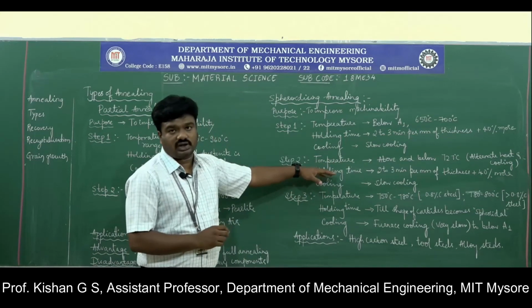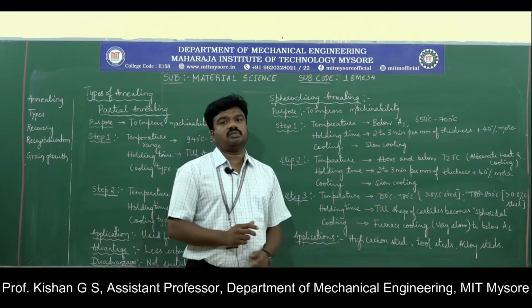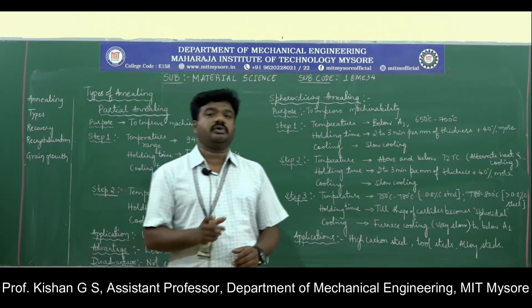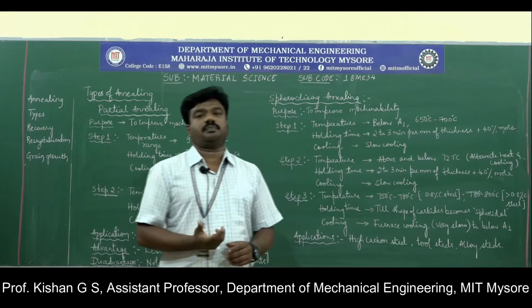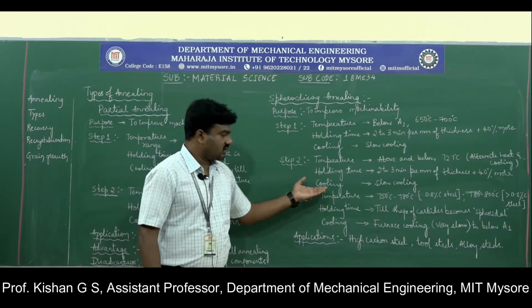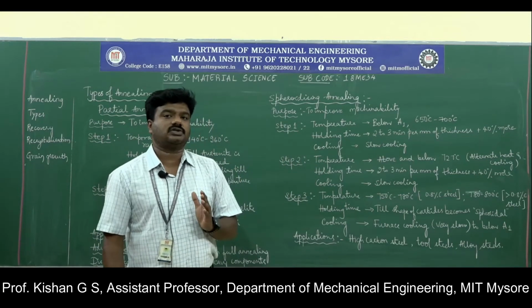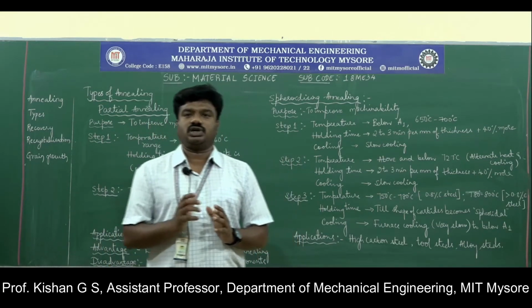Next comes the holding time. The holding time is similar to stage 1. It is again 2 to 3 minutes per millimeter of thickness plus 40% more holding time based on the thickness. And the last is cooling. Again, like stage 1, it is a slow cooling process, normal cooling included in stage 2 here.